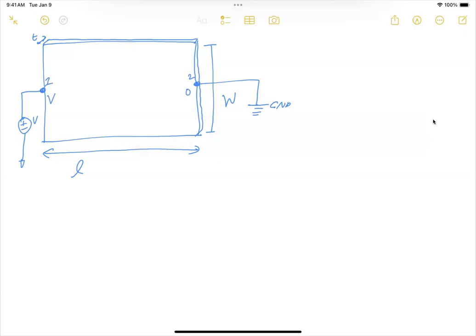So now the question was how to calculate the resistance, the equivalent resistance of this voltage plane, and also how to understand the current distribution in the cross section of this voltage plane, right? In this case, because the current distribution is going to be non-uniform, we cannot just simply use Ohm's law, rho L by A, to solve for the resistance, but rather we need to try to understand this from a more